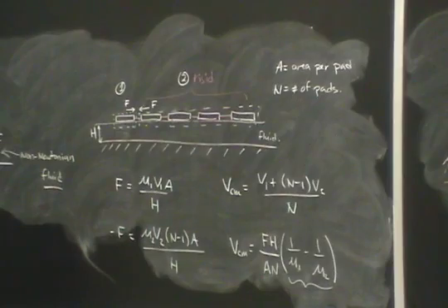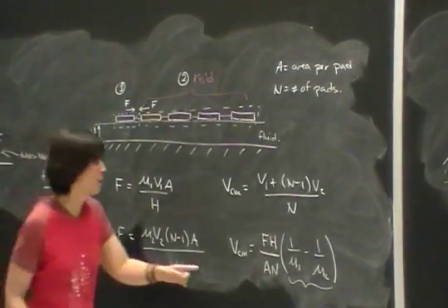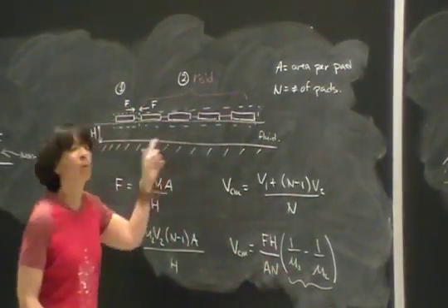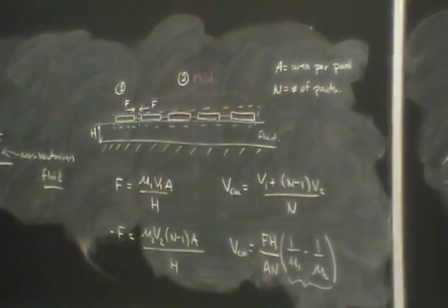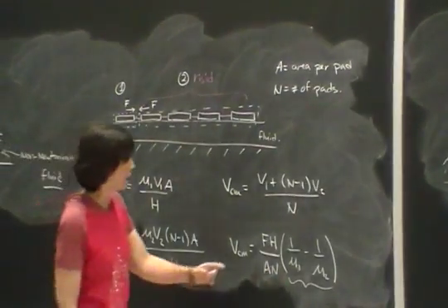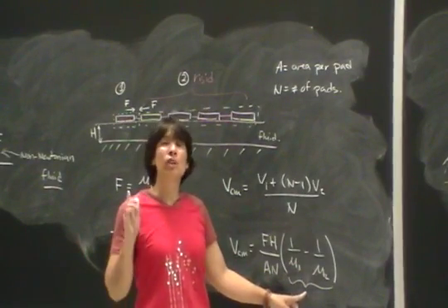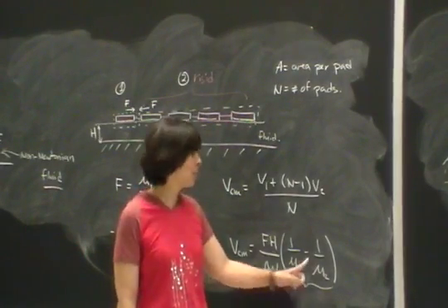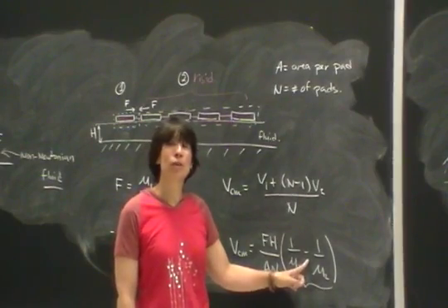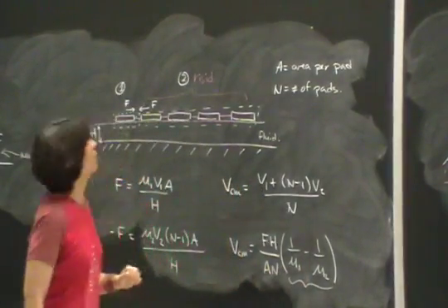As long as you have any kind of nonlinearity, that breaks the symmetry and you get something non-zero, and this thing will move. What's even more interesting is that the type of nonlinearity, so let's say shear thickening versus shear thinning, determines which direction it crosses, because there's a minus sign here. So shear thinning is going to go one direction, shear thickening is going to go the other direction.